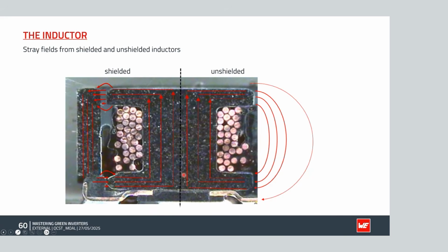That means that under temperature influence, be it the surrounding air temperature or the temperature from the board itself heating up and getting to its steady state, that temperature is ultimately coupling or conducting onto your inductor and raising its temperature. And that changes the behavior of the actual core material. With semi-shielded or shielded inductors with a small air gap, what we call hard saturation type components, you end up with a massive change in ripple current. And that can be quite disastrous from a functionality point of view. We're not talking here about just the EMI side of things.